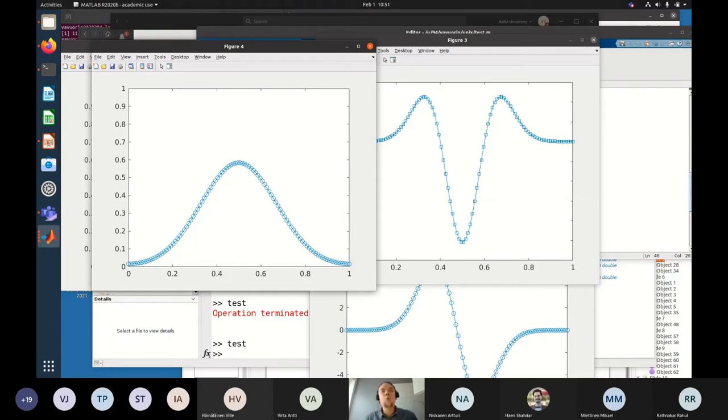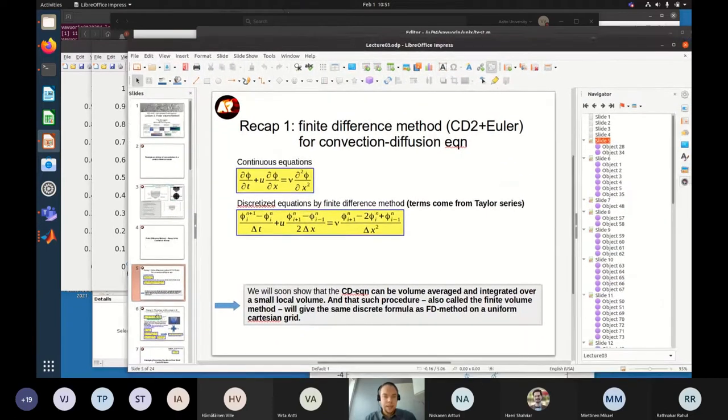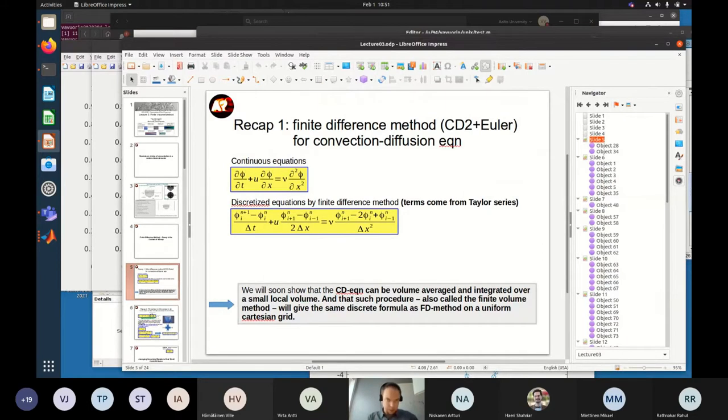And how do I know that this was a conservation law? Remember that the convection diffusion equation is a conservation equation, a conservation law. When we have this kind of equation, it's telling us that things are transported and they are diffusing by molecular diffusion or some other diffusion. But the physics is that this represents a conservation law. And the conservation law means that whatever the stuff is that's being moved, whether it's the number of smoke particles, thermal energy, or chemical species, unless we have chemical reactions or nuclear reactions, things should be conserved when we solve for this particular equation.